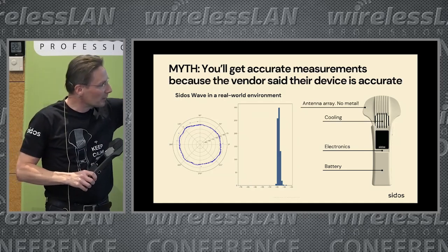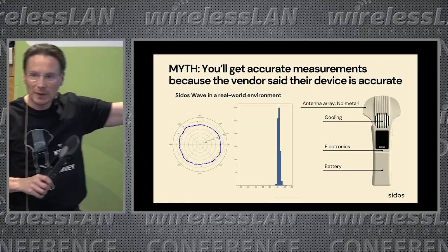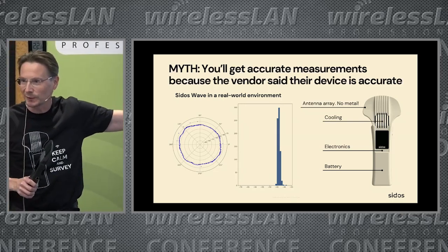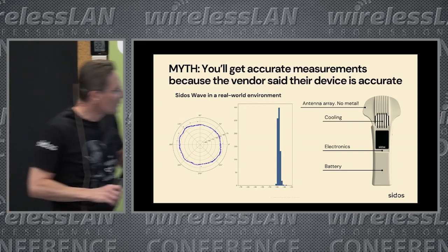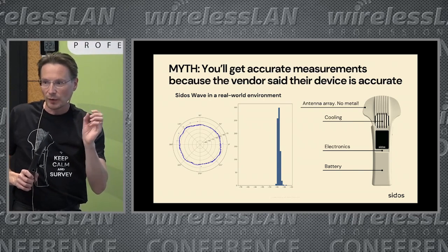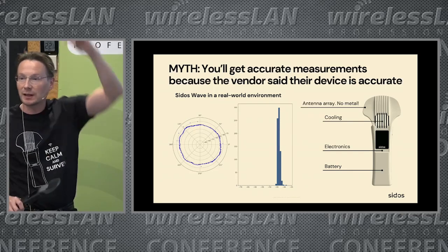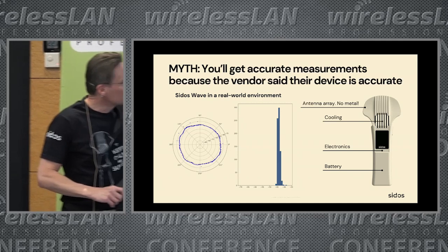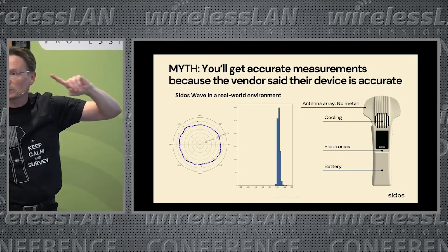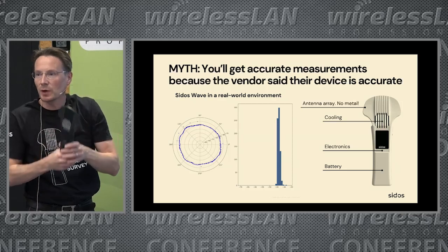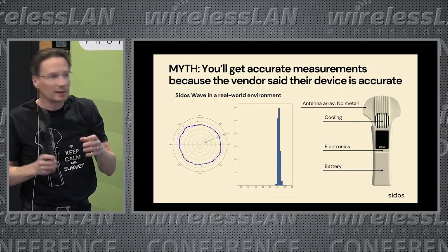The same data is in the histogram, and at the bottom there are small numbers. This is not made with PowerPoint; it comes out of a measurement software. You see these bins of certain RSSI readings, and the height of the bar is how many readings I got. All the readings pretty much are within plus minus 1 decibel. So when you rotate this, the results are within plus minus 1 decibel. Why is it important?